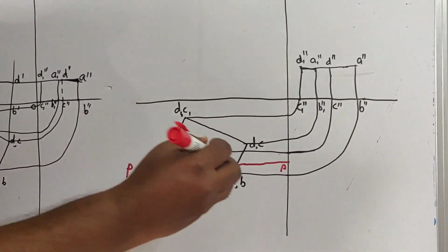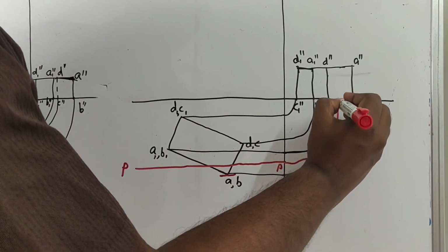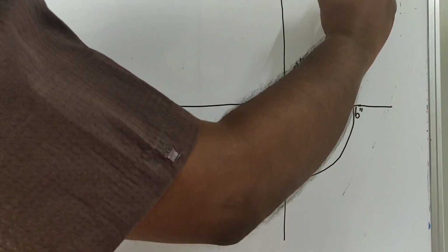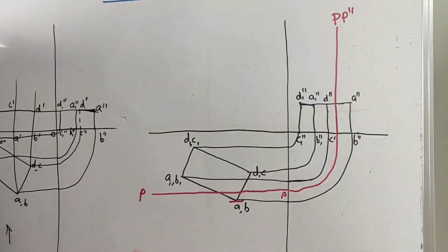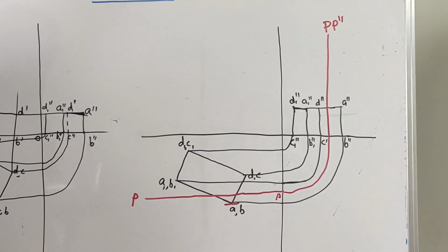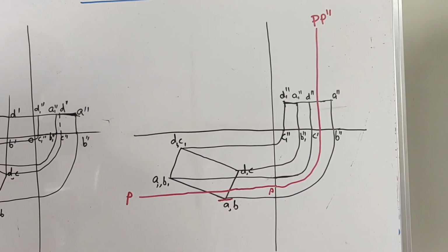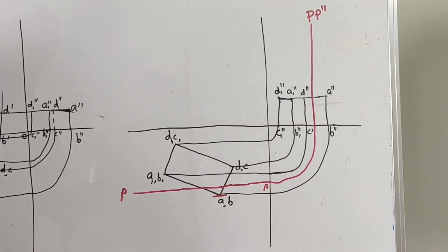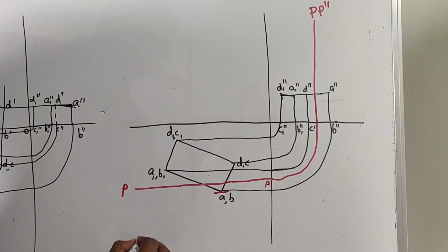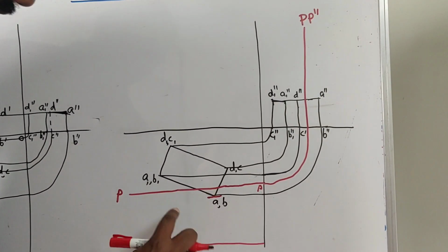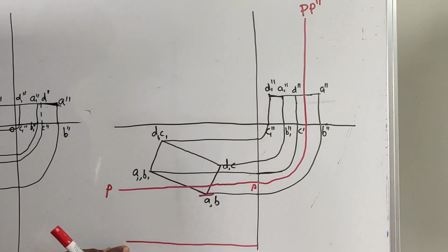Okay. Once you get the picture plane here, you can transfer the picture plane to the side view also. So this refers to the side view of the picture plane, that is PP double dash. Okay, that red line corresponds to PP double dash. Now we need the station point. In the question it is given that the station point is 70 mm in front of the picture plane. So you can have a distance of 70 mm from PP, and the station point will be somewhere here.